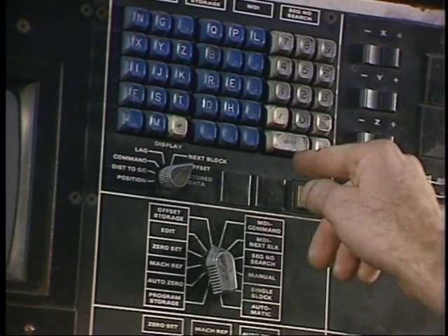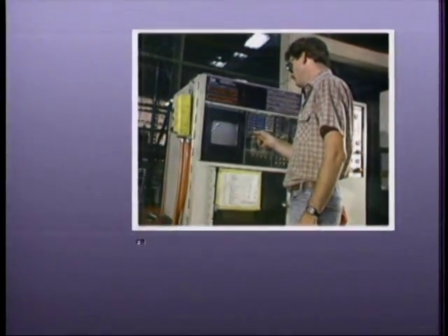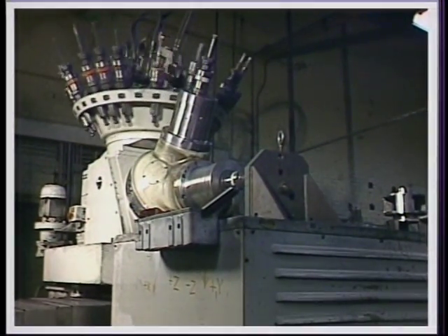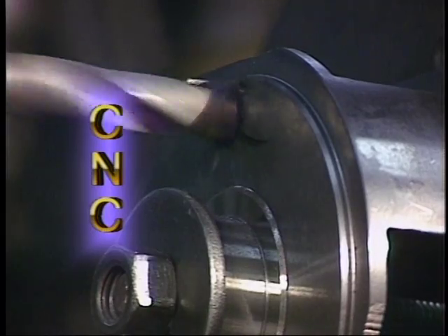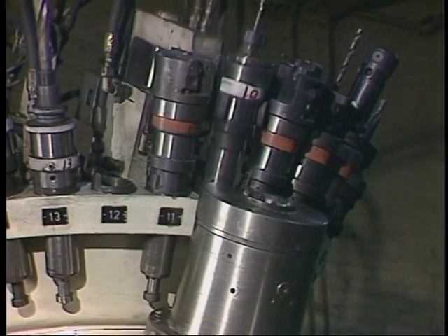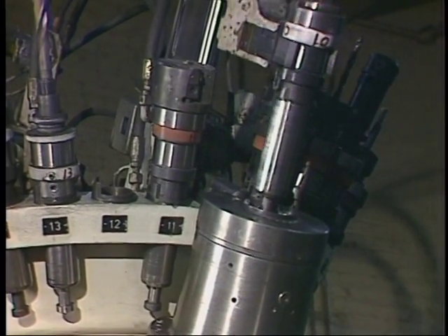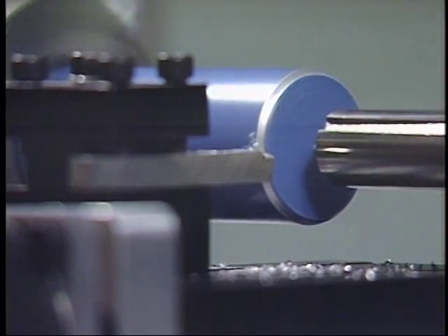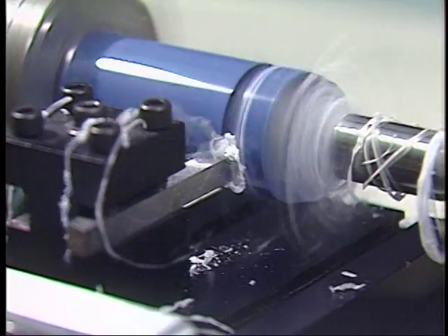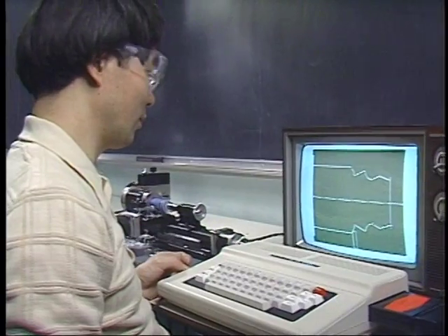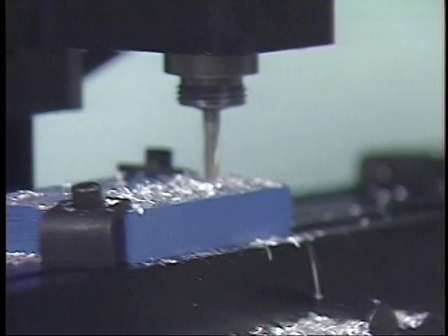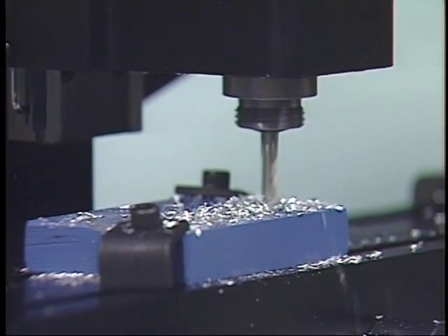Numerical control is a form of automation based on programs that control the operation of the machine tool. In modern NC systems, the control unit is a computer. The systems, called CNC for Computer Numerical Control, provide better performance by virtue of the great flexibility and speed of the computer. In the laboratory, tabletop machine tools retrofitted as CNC are controlled from a personal computer. The computer translates the part program into digital signals that are fed to stepper motors on the machines. The stepper motors control the positioning of the cutting tool with respect to the stock.